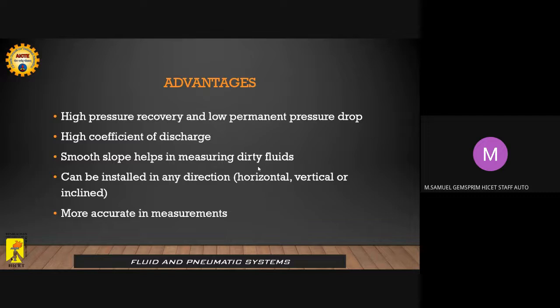Since the coefficient of discharge is high, obviously it will have lesser deviation from the original value. Then smooth slope helps in measuring dirty fluids that we have discussed. Then it can be installed in any direction. This is a very important advantage of this particular venturi meter. It can be fixed as a horizontal equipment or inclined equipment or even a vertical equipment. Then it is more accurate in measurements.